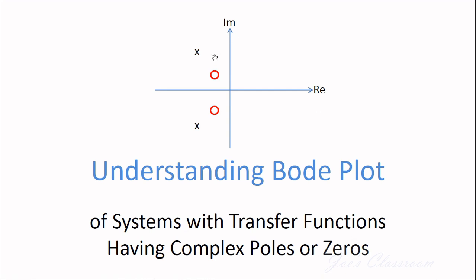So far, in all the pole zero plots which I have shown to you, I have marked the poles and zeros on the left side of the complex plane, the left half plane, LHP. The systems having all their zeros and poles on the left side of the complex plane are what we are going to call minimum phase systems.